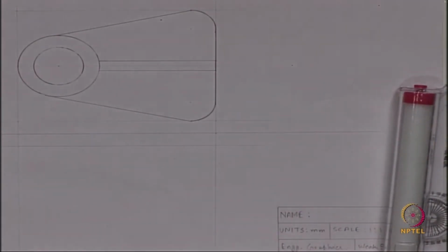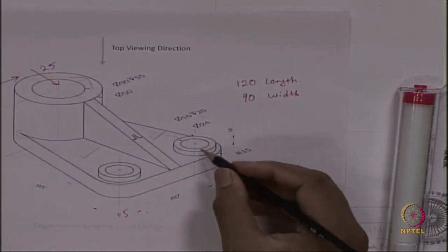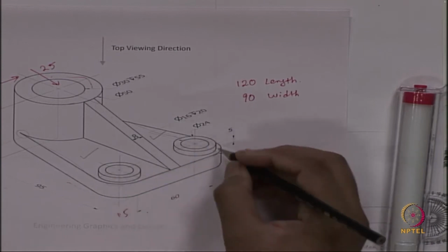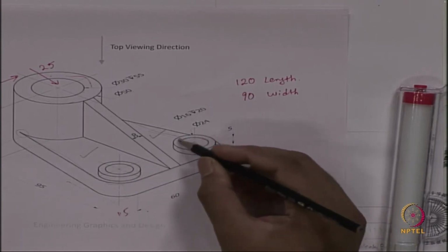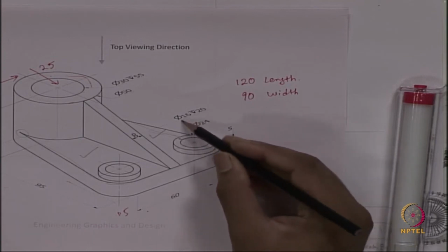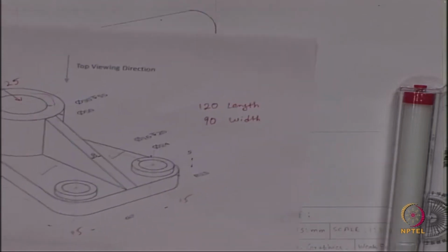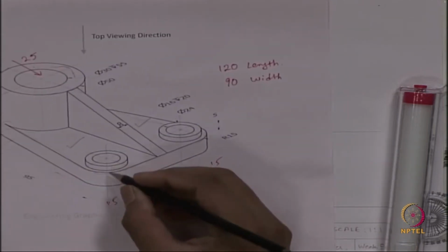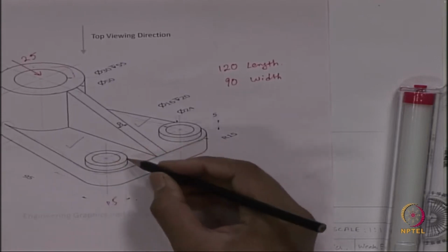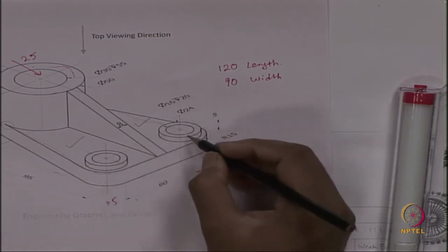What is the part left here? These two circular holes, and it has a boundary, like there is an outer dia of 24 and the inner dia is 16, and this is on both sides, and this is concentric with this arc. So, we will use the same center, but we will draw a circle of 24, then 16 on this side and on that side too.